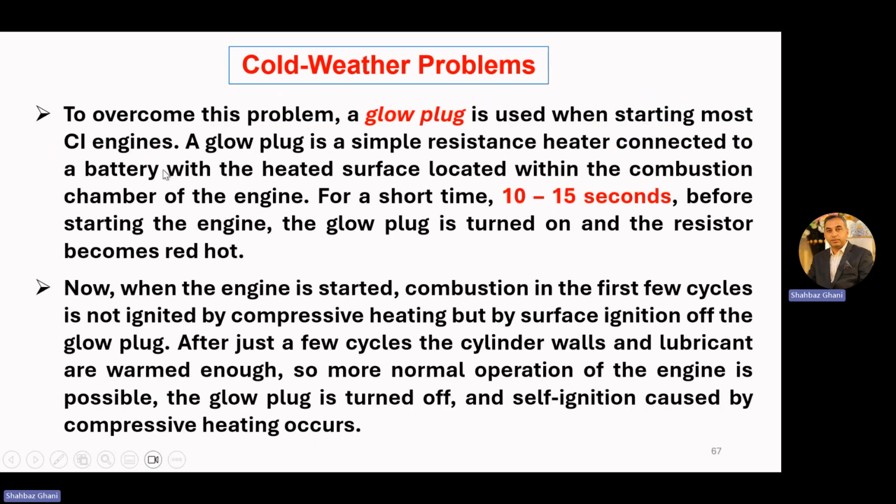So to overcome this problem, a glow plug is used when starting most CI engines. Remember, this glow plug is different than your spark plug. Glow plug is used in CI engines and spark plug is used in SI engines, and there is a difference between the glow plug and the spark plug.